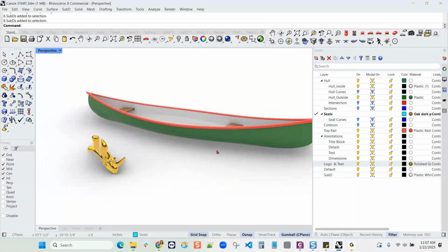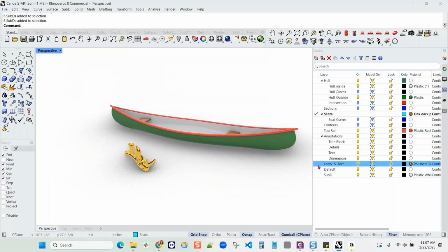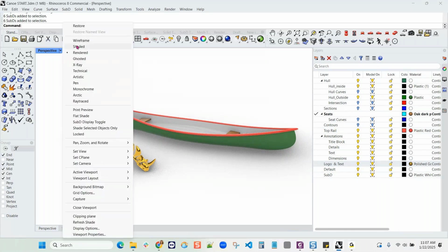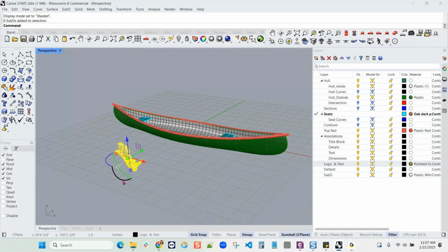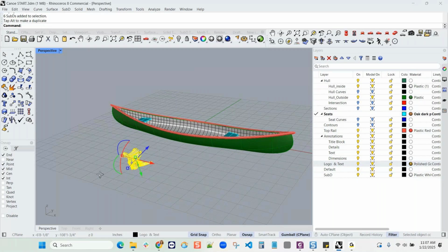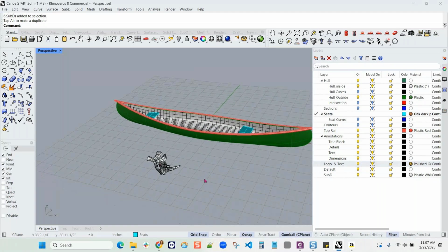And as you're learning Rhino, you'll probably read or hear that internally surfaces in Rhino are kept as rectangles. And if you want to see what that rectangle looks like, Rhino offers a command called Create UV Curve. So I'm going to make this shaded again, and we'll rotate the logo to be flat either now or later. But we're going to place the logo on the surface that represents this hull surface in UV space.